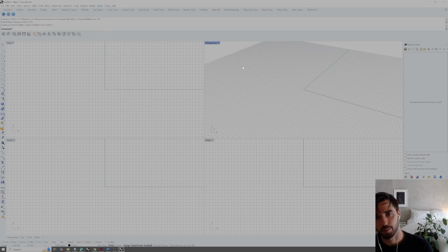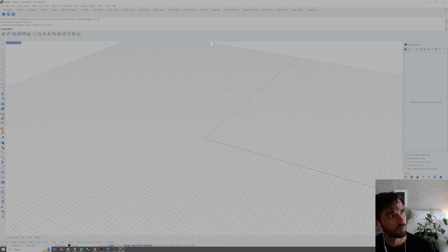So generally when we're opening up Rhino, we start with these 4 views, but typically I just double click on the name of perspective, and this expands that one viewport so that the only viewport in our viewing canvas is the 3-dimensional perspectival space.